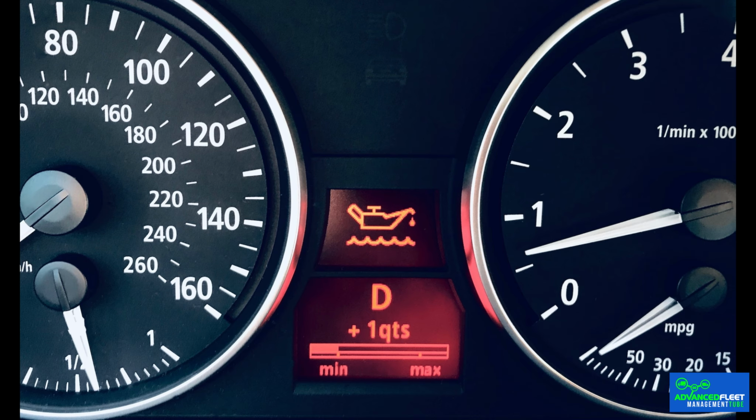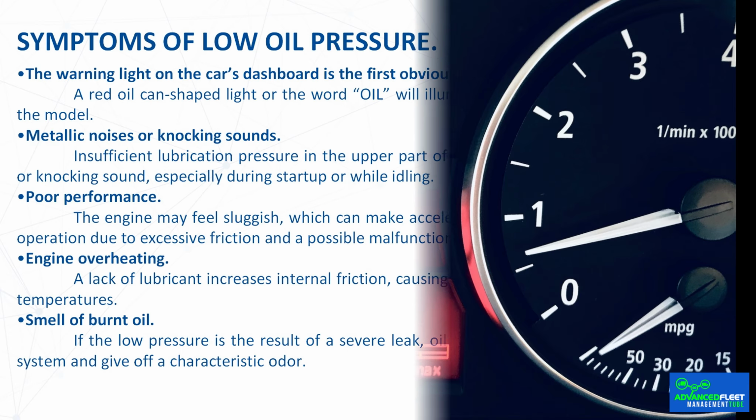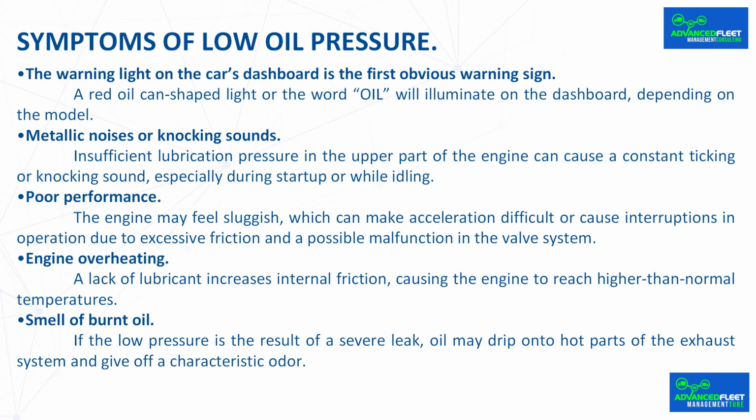Symptoms of low oil pressure. The warning light on the car's dashboard is the first obvious warning sign. A red oil can-shaped light or the word oil will illuminate on the dashboard, depending on the model. Metallic noises or knocking sounds. Insufficient lubrication pressure in the upper part of the engine can cause a constant ticking or knocking sound, especially during startup or while idling.